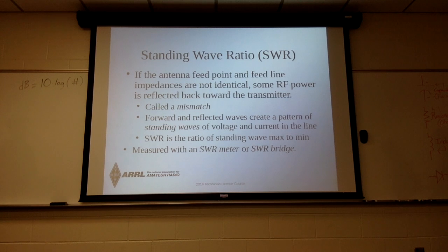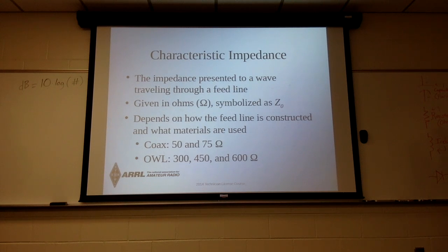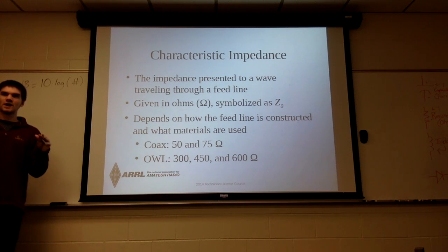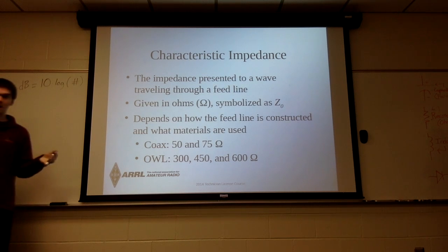What's the significance of the structure of the cable? The structure of the conductor? The conductors themselves. Right. It's electricity again flowing through. So what's the significance of having a coax or a... So the calculation of characteristic impedance is what we call a high frequency calculation. Normally if you're at DC, they're just wires. But wires aren't just wires when you move up to high frequencies, such as the ones where you would be operating your radio.